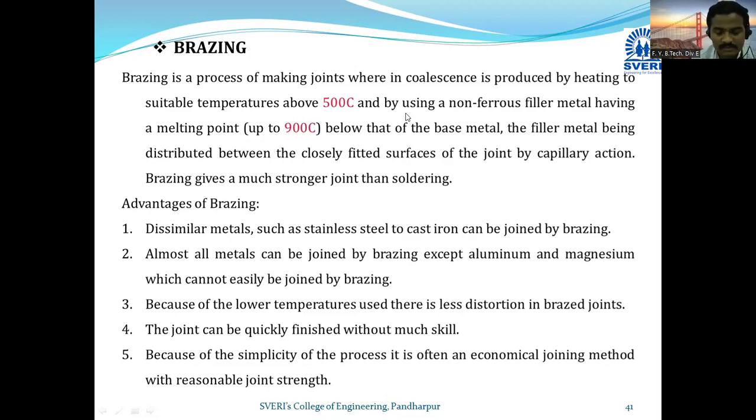It is the process of joining similar or dissimilar metals by heating them to a specified temperature above 450 degrees Celsius, but below the melting temperature of the workpiece or the metal pieces, and using non-ferrous filler metals or materials. Non-ferrous filler materials.